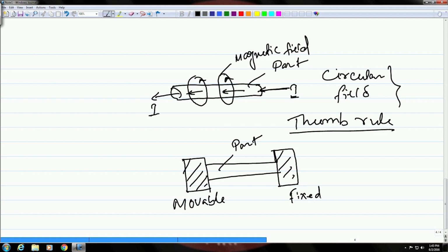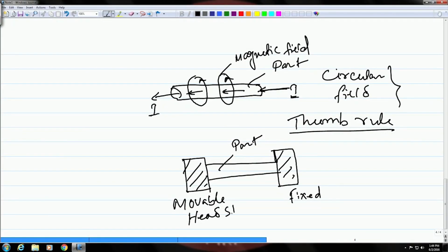Okay. So, you can move this movable part and tighten the part against the electrode, so that there is no loose contact, because when you are flowing electric current, loose contact is not desirable. So, the movable part is also sometimes called the headstock, and the other electrode which is fixed is known as the tailstock. Okay. So, then you flow the current from this to this.